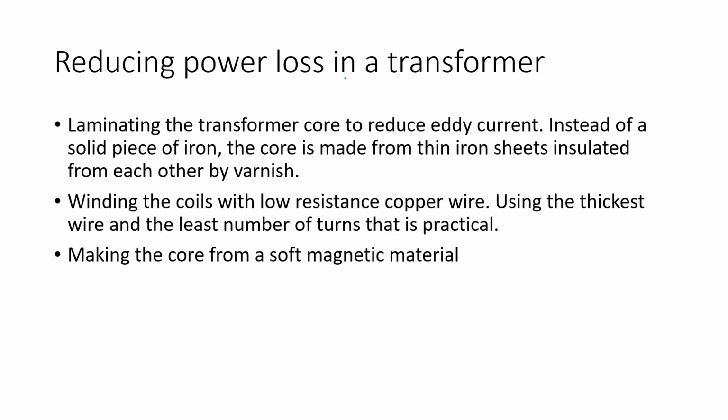It says winding the core with low resistance copper wires, using the thickest wire and the fewest number of turns that is practical.